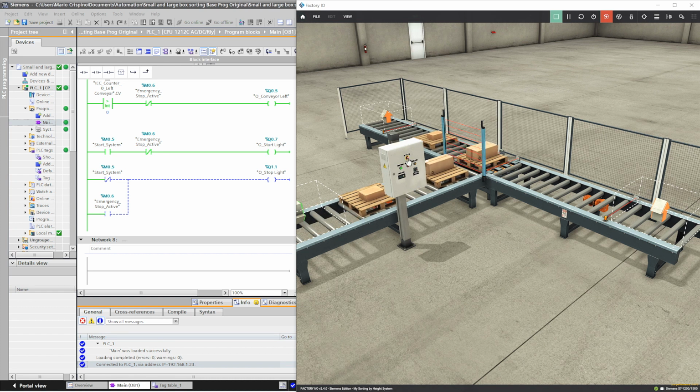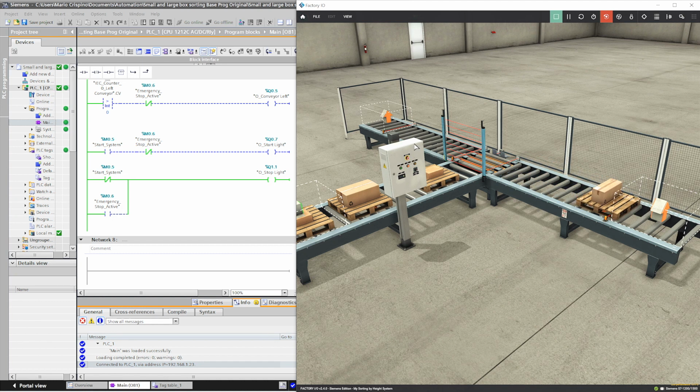Now let's press the emergency stop button and everything comes to a halt. Great, that works. Now let's see what happens when we release the emergency stop button. As there was a pallet ready to go onto the loader, that continues on, and the right and left conveyors start up again too, but the entry conveyor is stopped just like it was when the stop button was pressed.